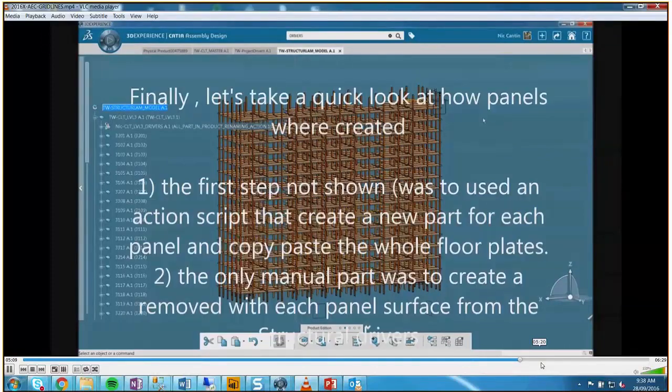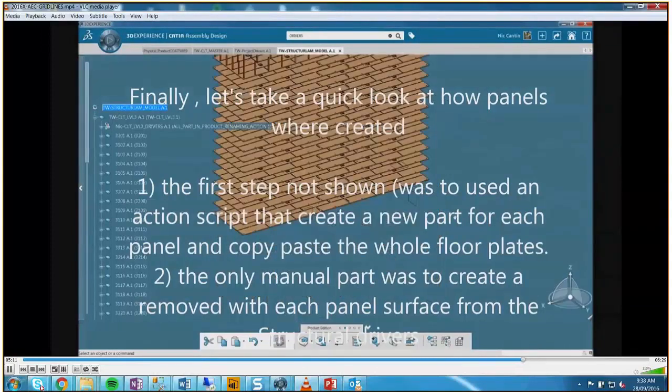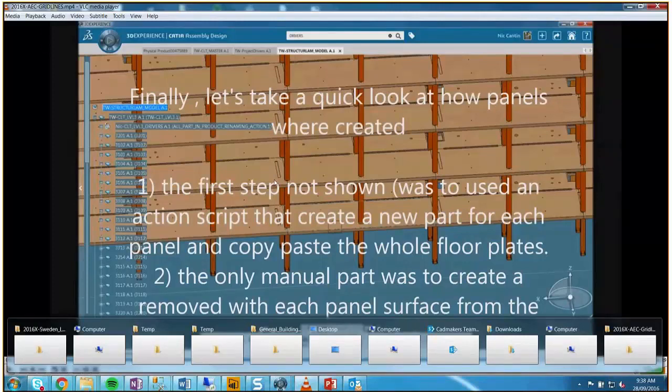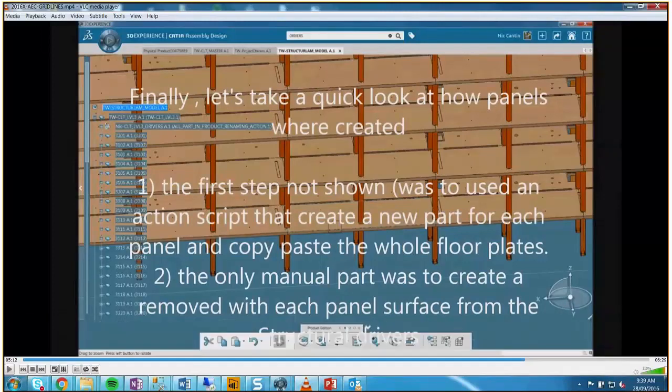So you had multiple contexts where you were updating the first level of control geometry and then the second level of dependent geometry, so that the model was partitioned in a way that you could update it quickly. Yeah, essentially we would update just the typical floors, and then it would propagate to the other contexts once we open those models, or flip back to that next tab. So yeah, you're exactly right. We were in multiple contexts to quickly update.